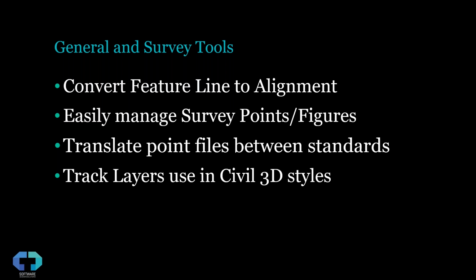If you have a need for working with different point files and specifically different point coding standards, oftentimes surveyors in the field are having to code in different fields or code sets. We can ensure that they work with one code set, and then you can make a translation before you import that into Civil 3D. So maybe you're converting from one numeric standard to an alpha standard, or from an alpha to a different alpha standard, depending on the coding standards you have to work in.